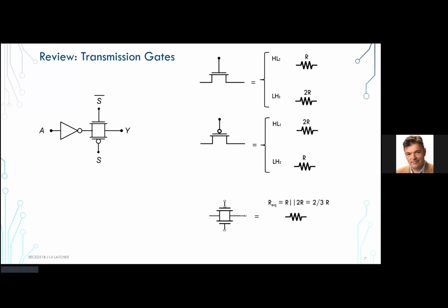Well, it's again 3/2 or 1.5. So the logical effort of both of those are going to be the same. The logical effort of the select input is going to be a little bit different because remember, I have 2 of those basically wired in parallel, and I have 2 of those acting in parallel. I have a higher load on the select input because each of those is sized as 1.5, 1.5. And those are sized 1 and 1, NMOSs and PMOSs.